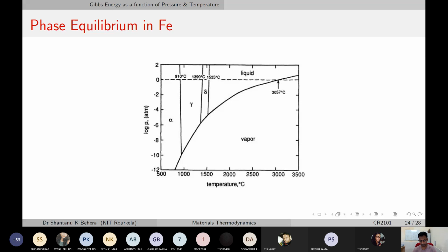Natural diamond is fairly expensive, but to be able to use its beneficial properties like lesser electrical conductivity, electrical insulation, higher thermal conductivity, and hardness, people are using certain carbon sources to produce diamond-like carbon, DLC. Okay. Likewise, that can only happen when you have a clear understanding of the pressures and temperatures and then stability of these phases vis-a-vis other phases of carbon.